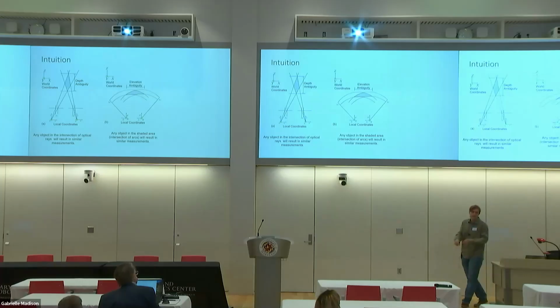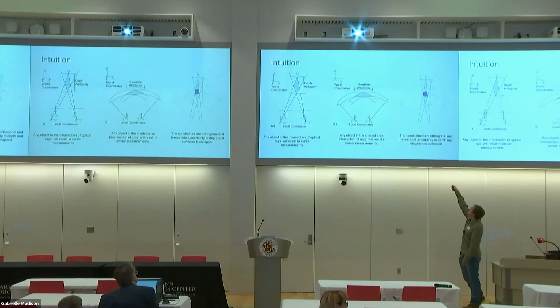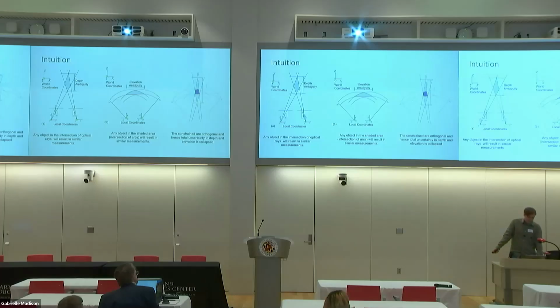By contrast, that sonar, which is projected onto the elevation axis, has an ambiguity in that direction, where here elevation is along here. Intuitively, if I have a point that I can register, that belongs here with the cameras, here with the sonars, I can combine those constraints and localize it both laterally with the camera and axially with the sonar.